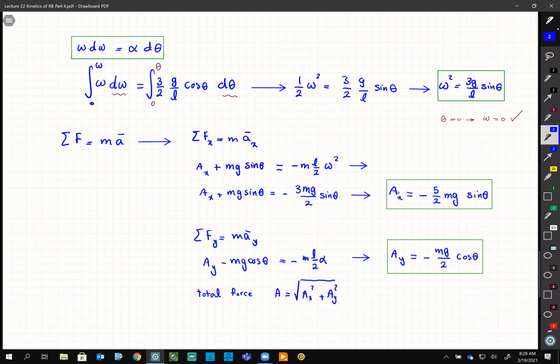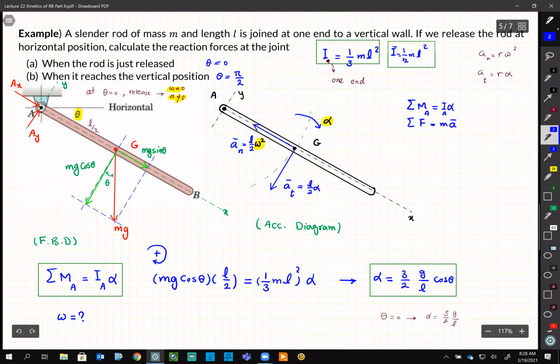Because remember in this course, we just tell you that A is a joint, right? But in fact, it's a bearing, a ball bearing or roller bearing, and you guys need to learn how to design it. And when we say design for a bearing, because we don't actually design bearings, we just go to the tables and pick one bearing. Based on the forces that we have, I say, okay, my forces here is 1,000 Newton. So I look up the table and I see, oh, okay, I need this bearing. And then there are catalog, which we look catalog and we buy one bearing so it doesn't fail.